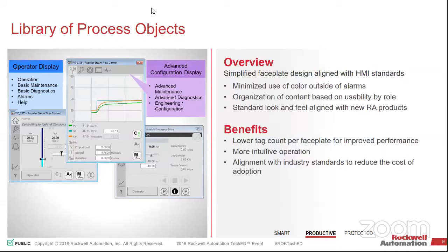It is very grayscale, and you'll see it when I show the demo. The only pieces that have color are anything that's moving. If it's a variable that's changing, like the temperature going up and down, that might be in blue. Everything else is going to be grayscale. If you see a bunch of color or anything blinking, that should be an alarm, or a reason to open up the block and figure out what's going on.